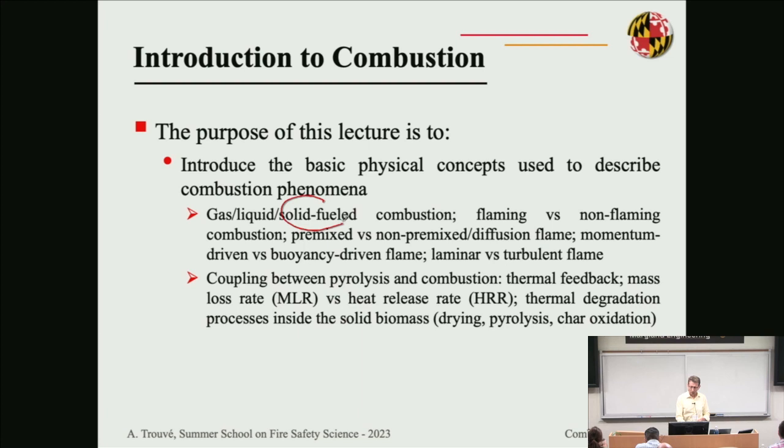So we are going to consider that our fuel is in solid form. We're going to consider primarily flaming combustion, primarily non-premixed combustion, and we're going to consider that the flames are buoyancy driven and that the flames are turbulent. And I'm going to go back to each one of these adjectives in the next few slides.